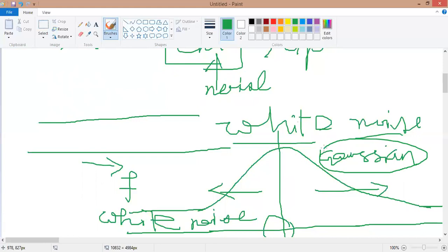If it is internal noise, it may be due to different components like resistors, or a diode may be responsible, because inside a resistor there is random movement of electrons through the conductor, and that will generate a heating effect, which may generate a noise effect, and that is known as thermal noise.